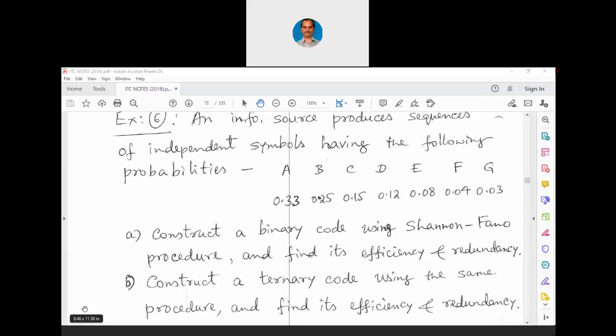For example, if the waveform is containing these three amplitude levels, 0 volts, 0.9 volts, let us say 0.9 volts is VDD, then 1.8 volts. Similarly, we can have 0 volts, 0.9 volts, 1.8 volts, and then 2.7 volts. If we have a waveform which is containing these four states, four voltages, then it can be a quaternary waveform, where using different waveform combinations, we can represent more information with a single waveform.